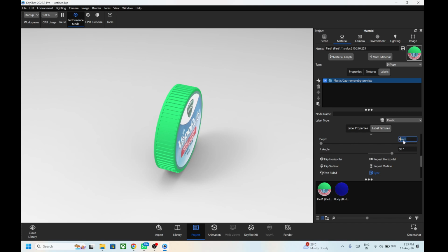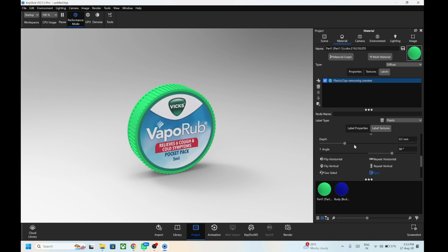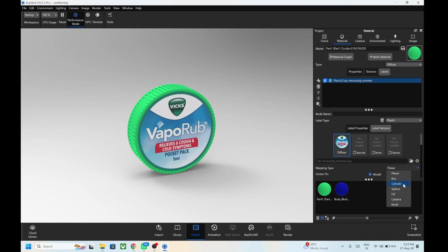to 1 mm or 0.5 mm is okay, 0.5 mm, so that while finishing after post processing, the sticker will remain. Otherwise there will be scratches and it will not be refined again. So that's why 0.5 is kept as a thickness. And next thing is that if this is not a flat surface, if a cylindrical surface is there, like a cylindrical bottle, and you want to stick your sticker over that, then instead of planar you have to select the cylinder, then it will act as a cylindrical sticker. Okay, so whichever the geometry of your model, you have to select likewise.